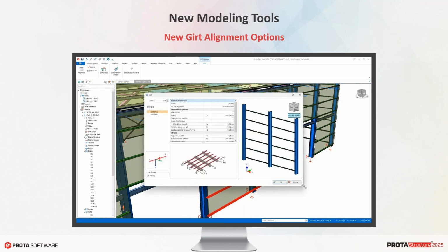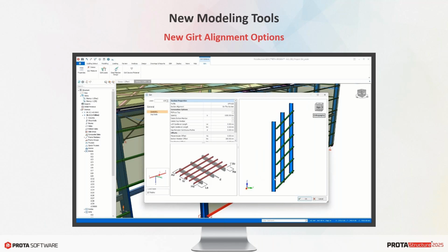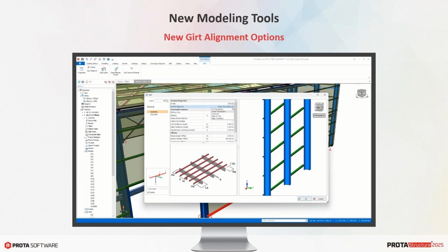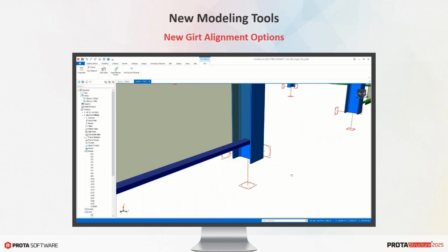One important strength of ProtaStructure is providing powerful tools to accurately create a physical structural model. For this purpose, we have developed macros for steel members, such as purlins, trusses, as I told before, and so forth. These macro members aim to provide a practical modeling experience, as well as a seamless detailing where you won't need any further editing. Girt section alignment options are now extended to support more variations, such as centered, aligned top, and aligned bottom.